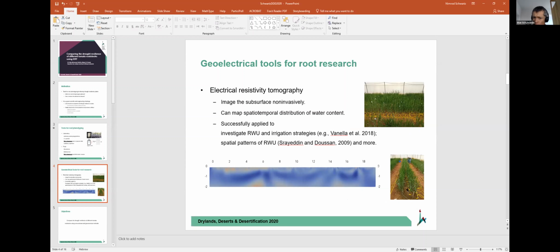And with all these electrodes, the computational burden would be quite large, right, to actually make sense of the data? Yeah, so of course there is a lot of computation behind it. What you get from the measurement is just a table with numbers, and to obtain this type of map, you need to apply an inverse algorithm. This is similar to what is happening in MRI, for example, where you image your body. So this is a similar algorithm, translating the data into a meaningful image.